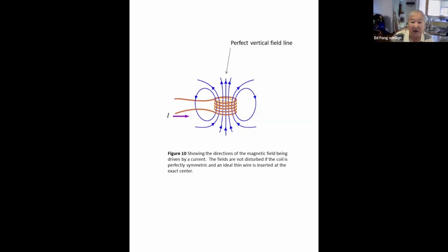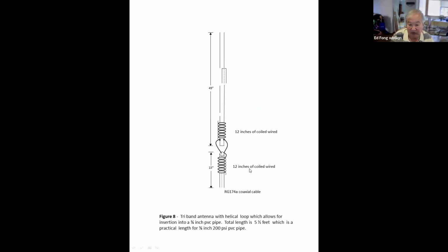So ideally, could you possibly wrap that 12 inches? Remember, you need 12 inches because that's the resonance for a quarter wave each way. Could you coil it up with thin coax? Remember, I said RG174, that's the thin stuff, not RG58 or RG8X. Could you wrap those 12 inches around? I mean, it's not perfect, but is it enough not to disturb the field, or at least still achieve dipole resonance, because you have a quarter wave at 220 up here, a quarter wave down here, here's the coax, here's the twin lead.